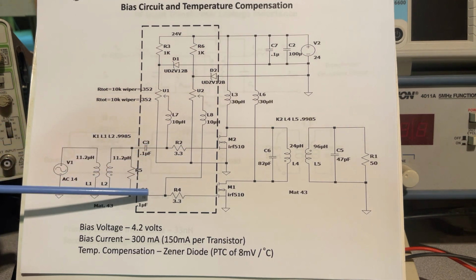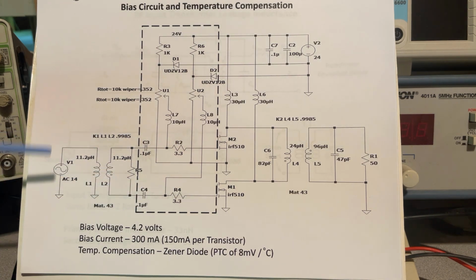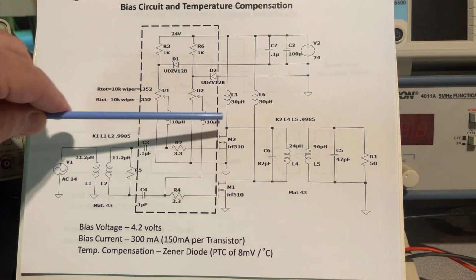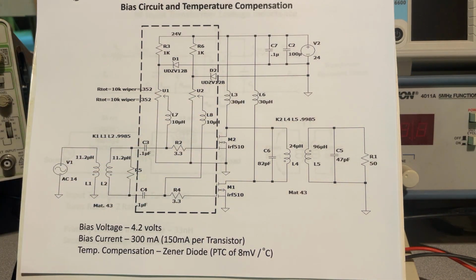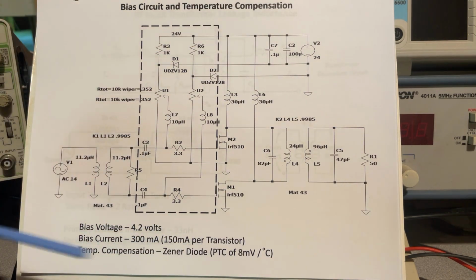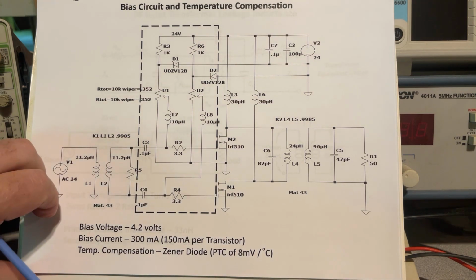Now in that demonstration, I just used a 50 ohm resistor, okay? But in later demonstrations, I'll actually show how we use LTSpice to measure the input impedance of this entire circuit. So that would include the AC coupling capacitors and the dampening resistors, and of course the impedance of the two transistors, the gate impedance. So today I just want to go through the input circuit and talk about some of the fundamentals, and then actually do some bench measurements and some demonstrations to show how this works.